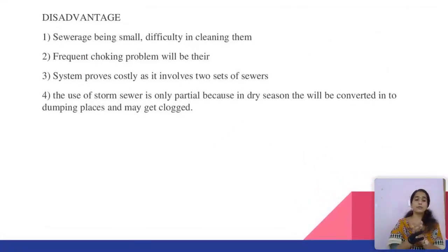Then the disadvantages of this system are: the sewerage being small, difficulty in cleaning them, and the frequent choking problem because of the small quantity of sewage. Then dilution is not happening. The treatment system should be technologically higher, and frequent cleaning of the filters has to be done due to the choking. And the third one is the system proves costly as it involves two sets of sewers.